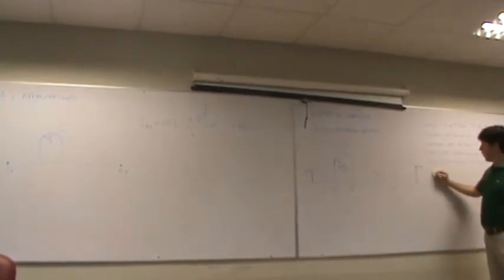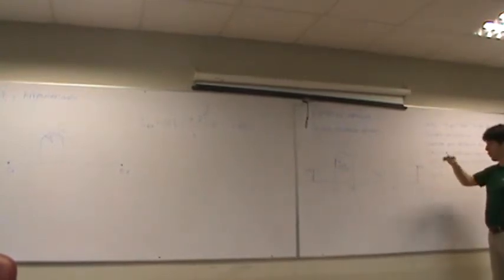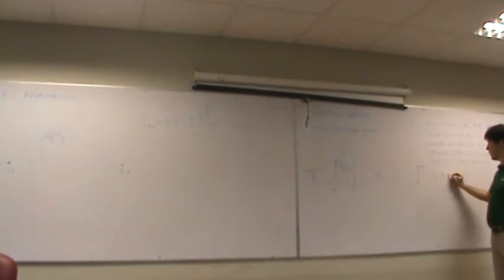And we treat this as a single knife edge obstacle. That is, from H1, from the geometry, we obtain D1, that is the Fresnel-Kirchhoff parameter.